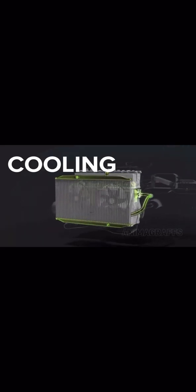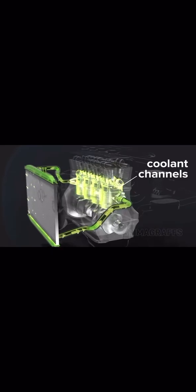Cooling. Engines get very hot during operation and require a cooling system. Coolant channels around the cylinders and through the cylinder heads carry a special liquid called antifreeze to keep temperatures within safe operating range. It's called antifreeze because it won't freeze in icy weather. After cooling hot engine parts, coolant circulates through the radiator.